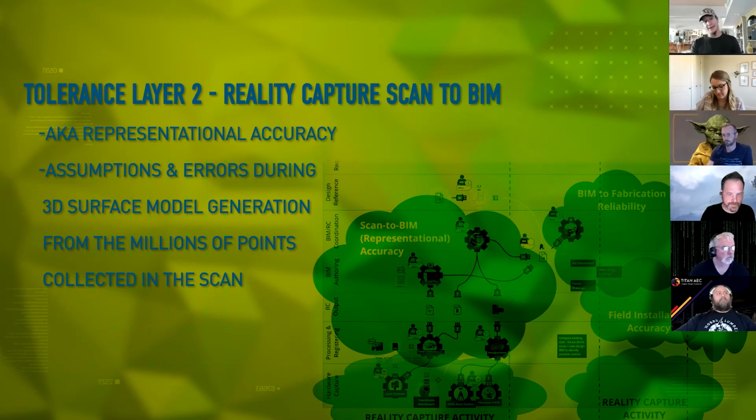So now you've got rotational accuracy of representation in plan and in section. You've got deviation between the actual surface and the abstract surface that you use to represent it. And then you have the question of how, back to human error, how accurately can one trace a point cloud? All of these things add error. I'm going to plug USIBD here again. They have a tool that's developed on the back of LOD, which I heard mentioned earlier. It's called LOA, level of accuracy.